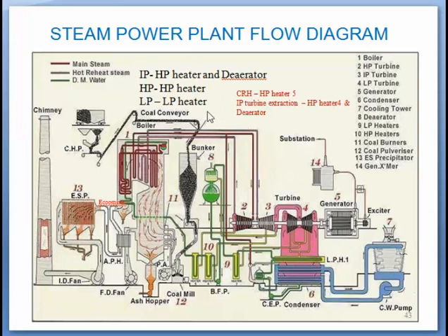In HP feed water heaters, the heat is transferred to the feed water by the bleed steam drawn from HP and IP. You can see here, one is going to HP heater number 5 and one extraction is coming from IP turbine which goes to HP heater number 6.